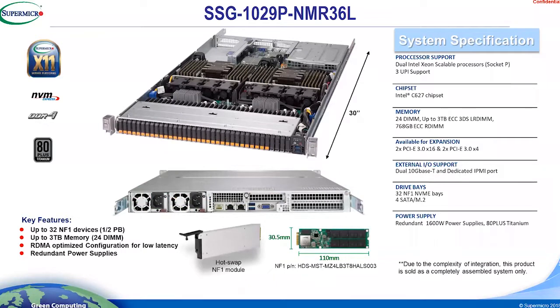And so this kind of summarizes that. You can see what one of those drives looks like down at the bottom, and it shows that it's 30.5 millimeters high, and then that same 110 millimeters that's used for the M.2. And if you look at that connector really close, it looks just like an M.2 connector. And that's where Intel and Samsung kind of parted ways. Samsung was very much saying, we need to have backwards compatibility to M.2. Intel said, no, that's not really important to us. We want to focus on a different form factor.